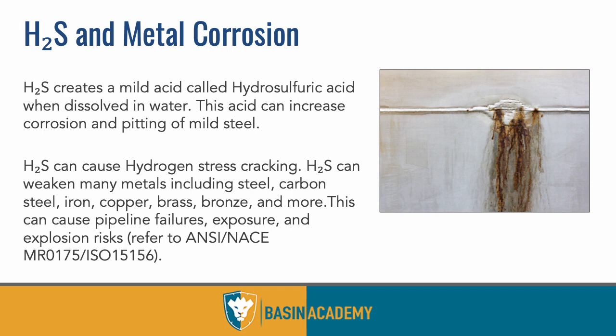So again, I kind of mentioned this on the last slide, how hydrogen sulfide bonds with harder metals. So a lot of times tanks will be lined where we know there's going to be H₂S. They'll use different metals that aren't as porous, so that H₂S can't bond with the metal. There's a lot of different tactics we can use when we know we have H₂S. The problem is, in our industry, wells have a tendency to become sour over time.